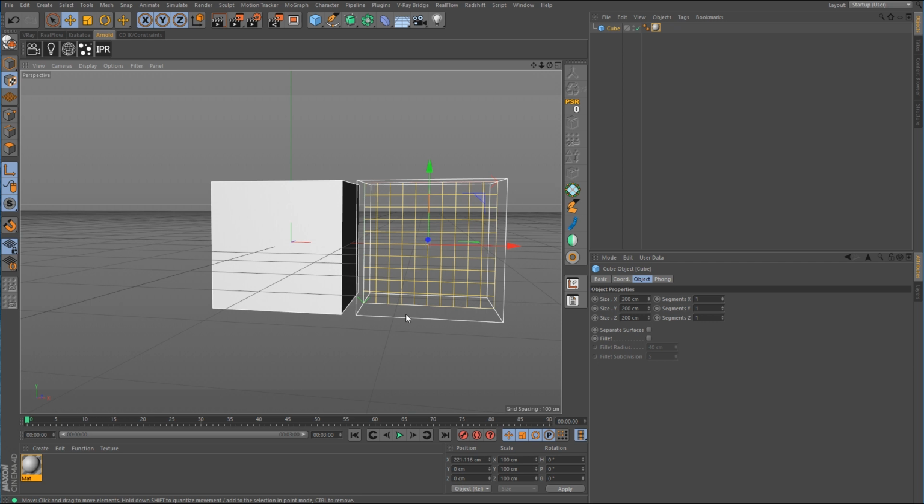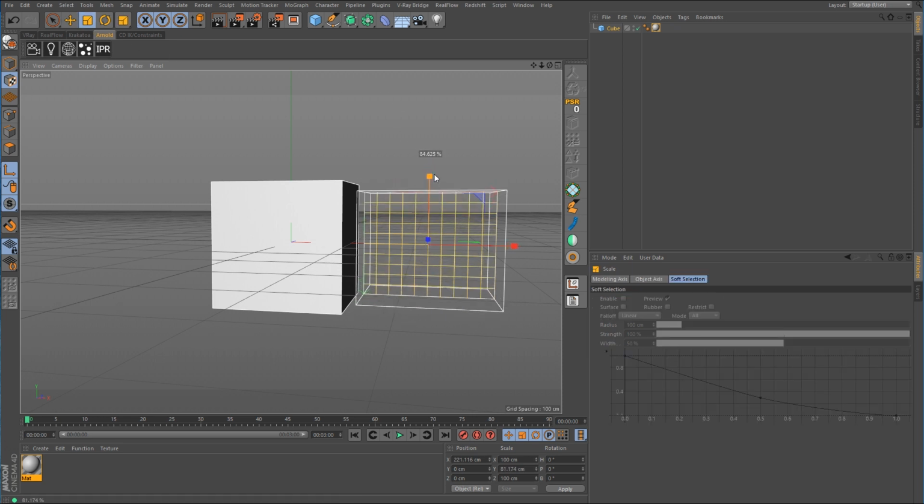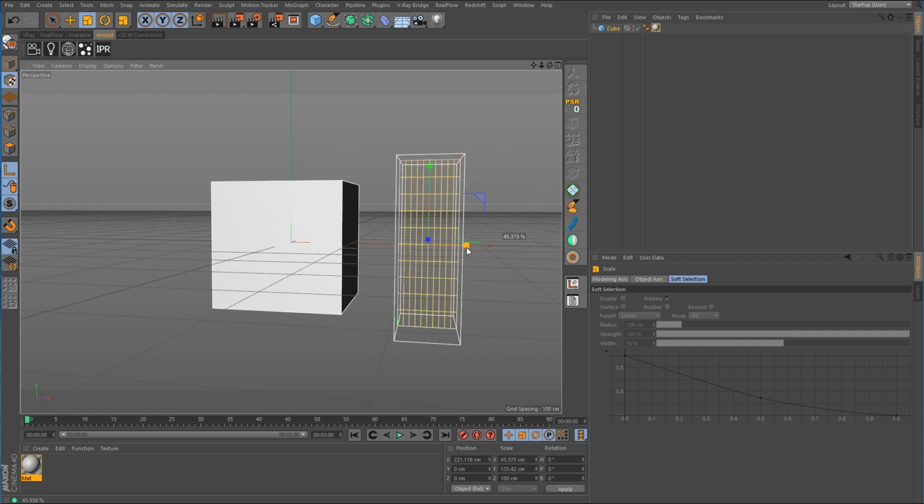This is the ratio that's going to be used when this grid projects your image onto your object. So if you have an image that's 16 by 9, 4 by 3, or some other ratio, and you don't prep it ahead of time, that means that image is either going to be squashed or stretched in order to fit this 1-to-1 grid. So I always like to prep my images ahead of time in Photoshop to make sure that it's a 1-to-1 ratio. That way I don't have to use the scale tool in order to squash and stretch this grid to get things to line up properly.